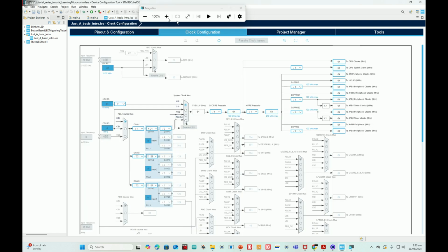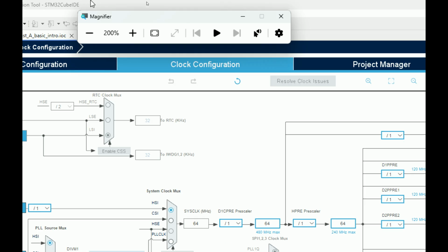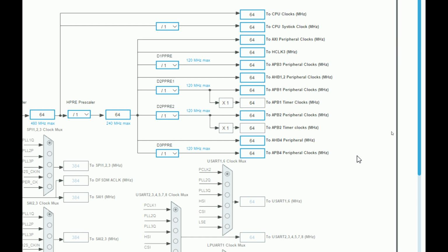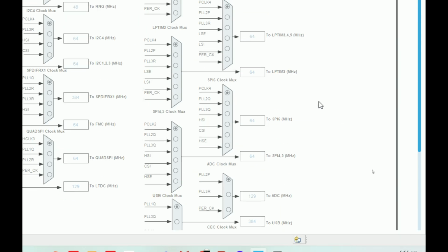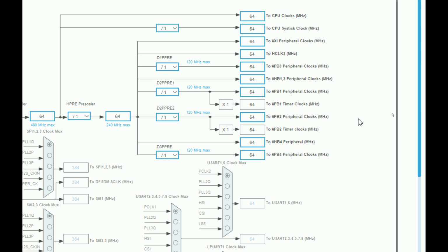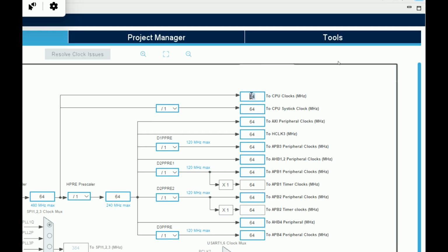The last thing is the clock. Okay, you can see the clock over here. Now what I told you is that the crystal you have on the board can be 48 megahertz or 72 megahertz. The maximum I have seen is 72 megahertz. Here it says that you have a 64 megahertz on-board crystal. Okay, there can be a 64 megahertz crystal on the board, which is just fine.